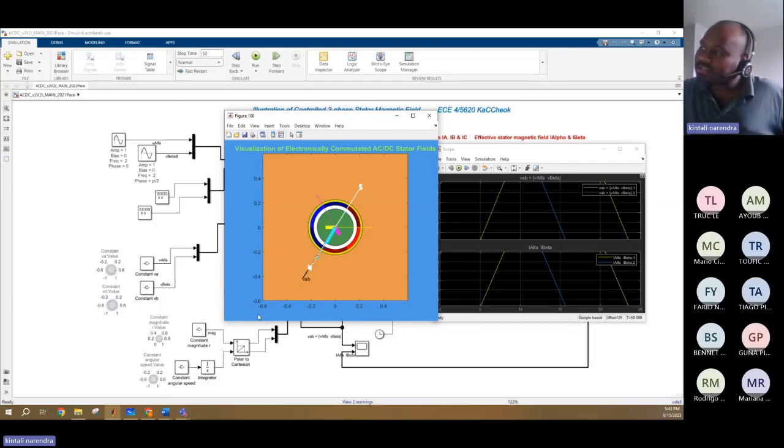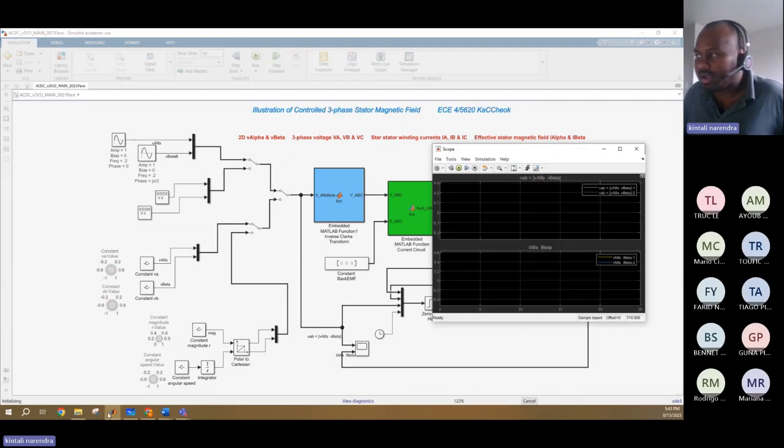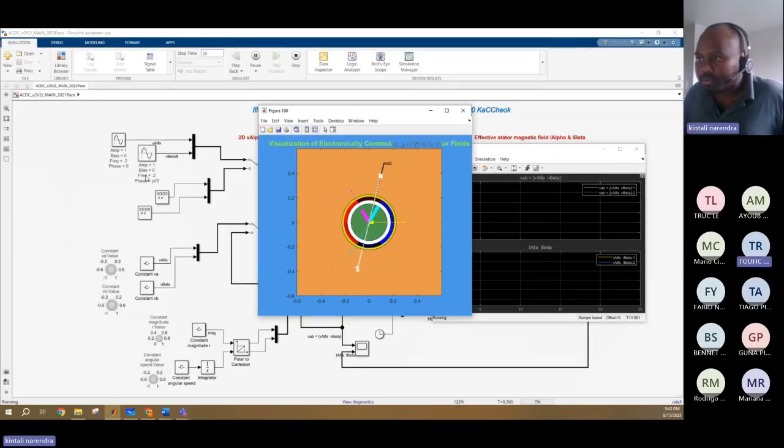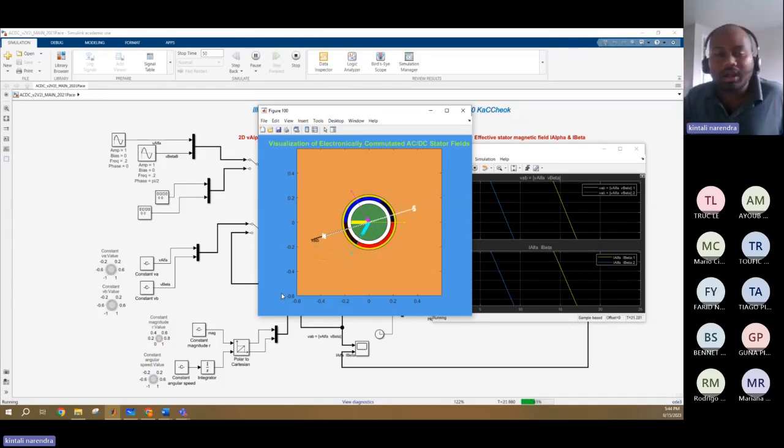Now that we know that the stator magnetic field is varying. See, north pole and south pole of your stator are varying, because you're providing an AC sine wave. And because of the sinusoidal winding which you did, you developed a magnetic field which is rotating. Now, inside this, the green, you can think of it as a rotor. The rotor also is a magnet which keeps following this stator at the same speed, because this is called a synchronous motor. Both the stator and the rotor rotate at the same speed.